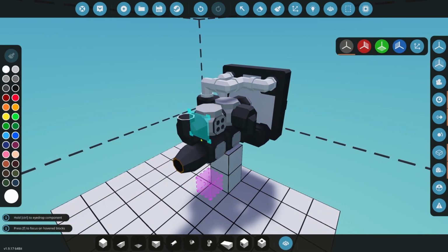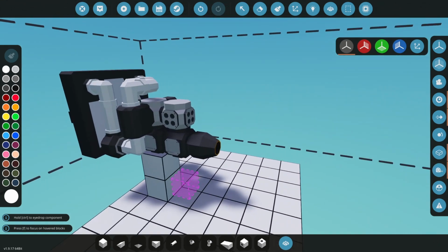We're going to go ahead and we're going to do supercharging. Supercharging is using the power of the engine to turn something that will then blow air into the cylinders. It allows us to pack more air in. The more air we take in, the more fuel we can burn, the more powerful our engine can be. This will cause more heat. Burning fuel causes heat. So the more that you put in there, the more heat you're going to produce. So we will go into that.